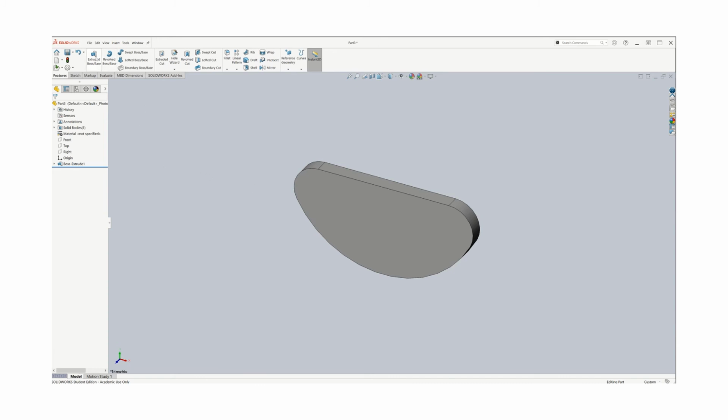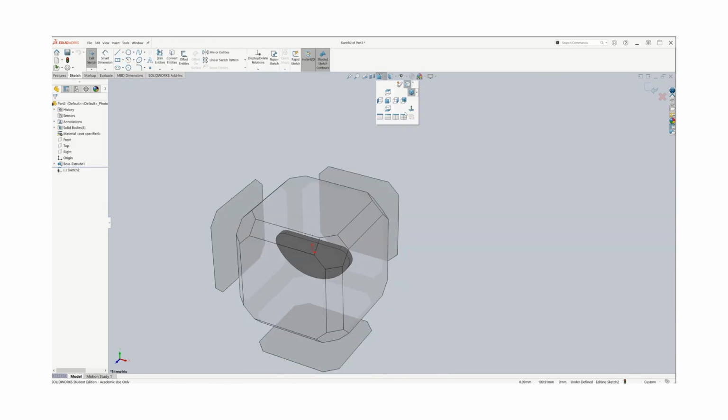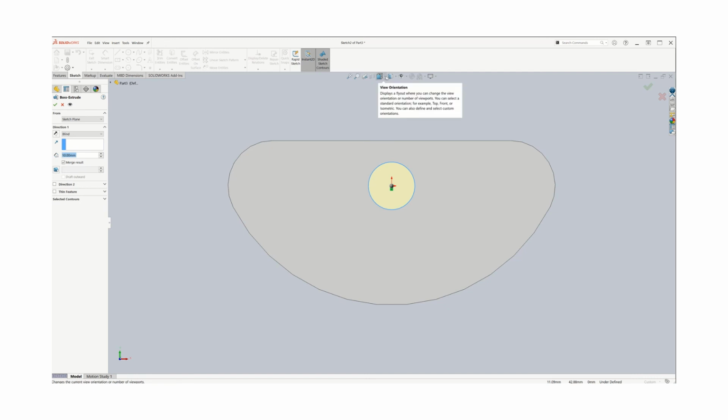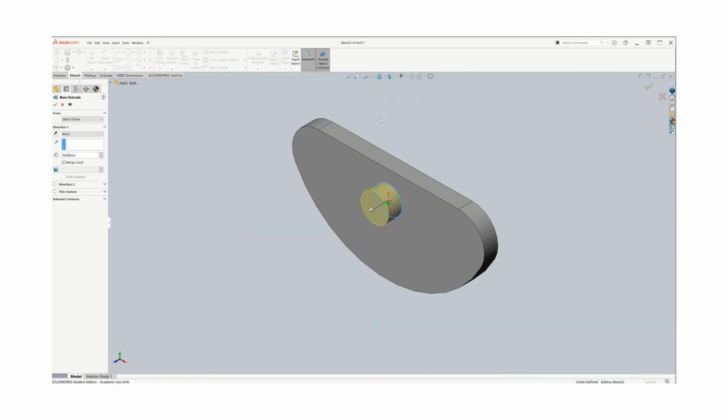And then I told you that I will show you some of the options that you have. So if I have the extrude boss base, and I choose this plane as the base plane for the second element, then I will just simply draw a circle. So I will draw a simple circle, and I'm going to have this cylindrical shape. Again, I have a choice of the perimeter option for the circle. In this case, I choose the first circle, and draw this. And if I want to try to extrude in that direction, let's see, to see better, that's what you have. Oh, but that is not what you want.